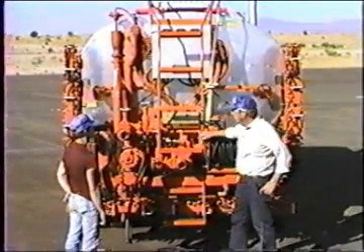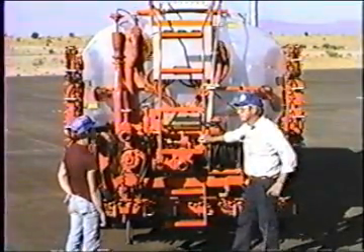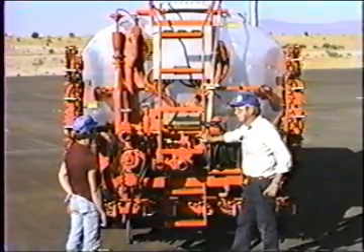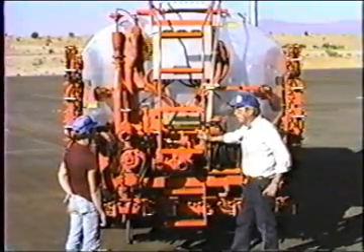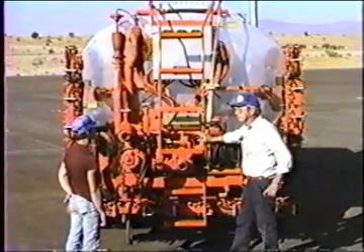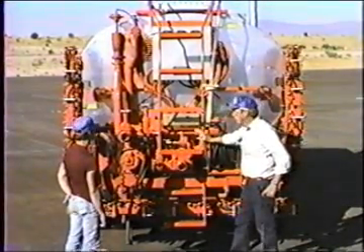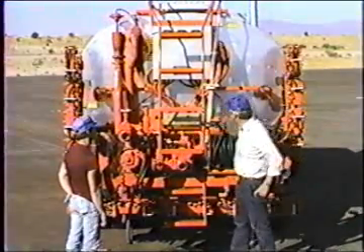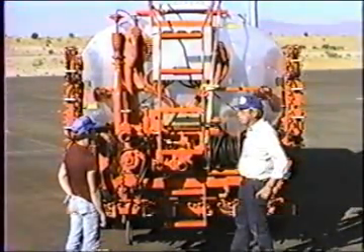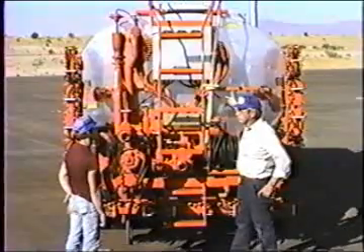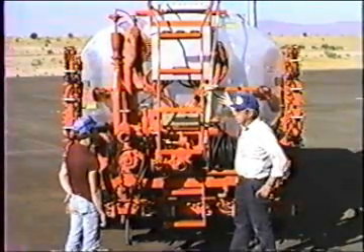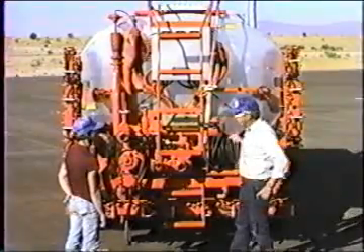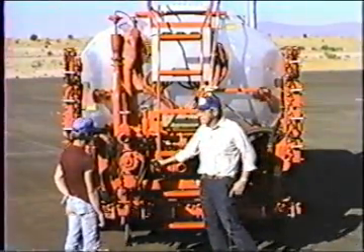When we do that, we're going to starve the pump. Anytime we starve any kind of positive displacement pump, it'll rattle, and it'll rattle like mad just for a few seconds. No harm done, it doesn't hurt a thing. You probably won't even hear it. Well, you will on this one because you're closing the valve while you're standing here. If it were a cab controlled one, you would close it up there and you'd never hear it because it'd be done rattling by the time you got here. Close that, it'll rattle. Open this.